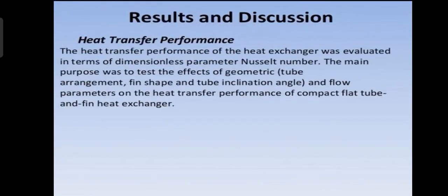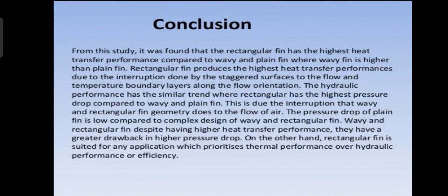Results and discussion. I came to the conclusion regarding heat transfer performance. The heat transfer performance of the heat exchanger was evaluated in terms of the dimensionless parameter Nusselt number. The main purpose was to test the effects of geometric parameters, namely tube arrangement, fin shape and tube inclination angle, and flow parameters on the heat transfer performance of a compact flat tube and fin heat exchanger.